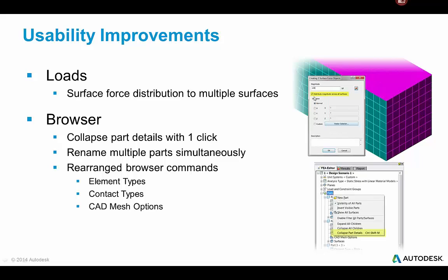In this release, we've added a checkbox that says, if I'm adding this 100 value to multiple surfaces, and in this case, this image is showing 3 surfaces, this 100 will be distributed to those 3 surfaces based on their surface area. So if these side surfaces are, for example, twice as much in area compared to this one, so it would be 2, 2, 1, a 5 unitless surface area. Then this 100 would be divided such that you would get 40 newtons here, 40 newtons here, and then 20 newtons here. And so it's just a good way of applying force to multiple surfaces.